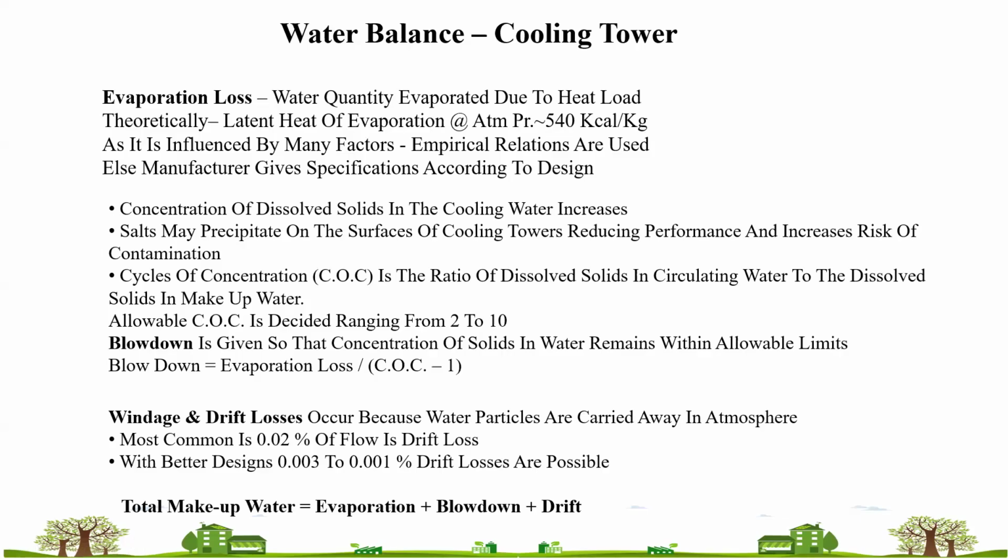Another probable reason for poor cooling tower performance is that you are not maintaining the liquid to gas ratio as the standard, or what is typically desired by the L/G ratio. It means you are circulating too much air relative to water, so your cooling tower performance is going to deteriorate.